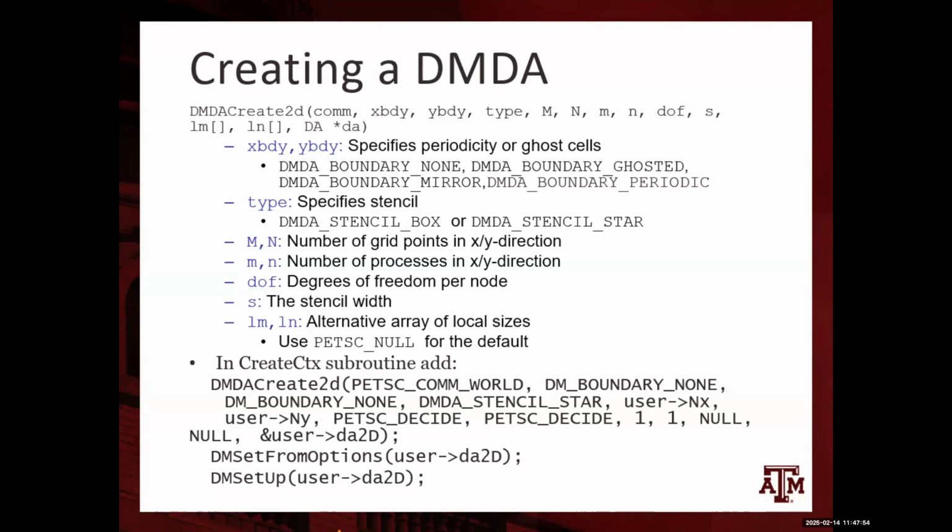This is i minus 1 here. There might be at most this i plus 1, which is on the other one. So we only need 1 node, correct? That's the ghost node that we need from the other domain, so that information can be passed on. That's the ghost node that I'm talking about for information passing between different nodes.